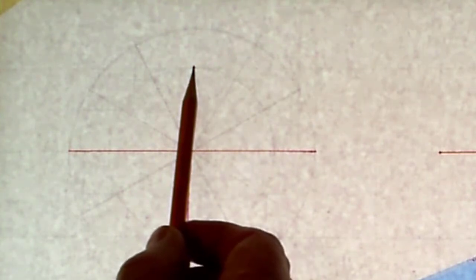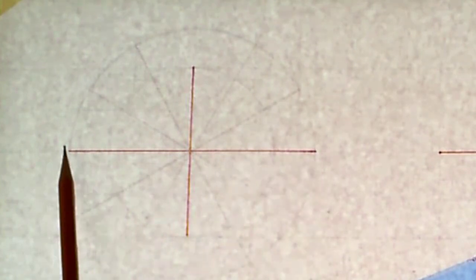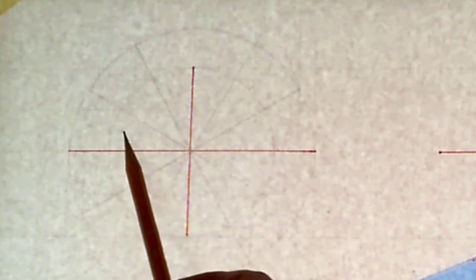Now, with the major and the minor axis, I already have 4 points established on this ellipse. The top point and the bottom point are the two extreme points on the minor axis, and the left-hand side and right-hand side are the two extreme points of the major axis. What I want to establish are the points in between. Because I've divided the two circles into 12, I'm going to establish 12 points. I've already got 4 points established, so I'm going to establish the other 8 points.